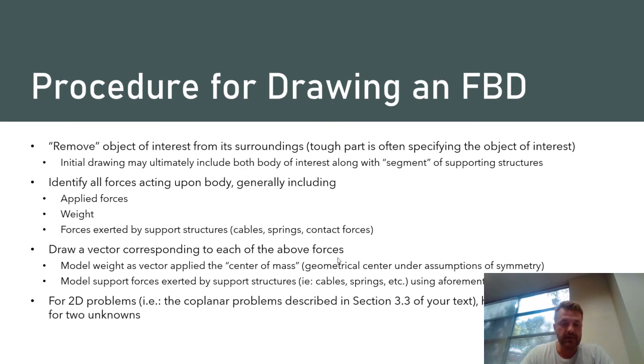If you have a support force, do whatever is appropriate for the particular type of support structure that you're dealing with, whether it's a cable, a spring, or so on. So for both cables and springs, the direction of those forces is directed along the actual geometry of the spring or cable itself. You may or may not know the magnitude in each case. For a spring, the magnitude would be proportional to the displacement, as we mentioned.